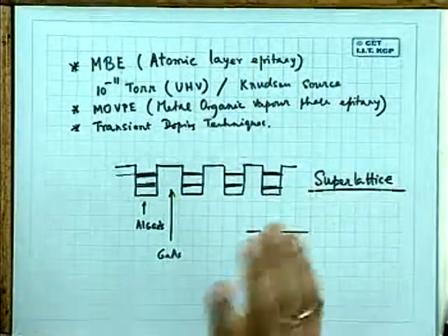Tunneling is a process which does not take place only in one direction. This is called Fabry-Perot interference. That is why it is called resonant tunneling. It's just like a Fabry-Perot interferometer. Photons go on traversing between the two mirrors and go on adding in phase, and that's how we get a very narrow response. That's the basic interferometric principle of the Fabry-Perot interferometer.